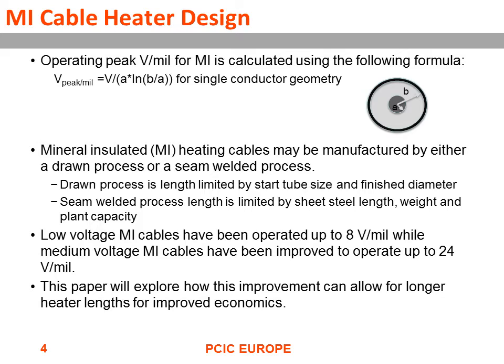MI cable has been typically very sensitive to volts per mil in past applications, and no processed MI cable is operated at above 600 volts. In fact, IEEE 515 specifies that the megger tests have to be lower than they would be for polymer insulated cables, so you don't have some destructive characteristics that you apply to the MI cable, because it seems to be a combination of continual stressing that'll help the failure modes, and there's a number of failure modes for MI cable.